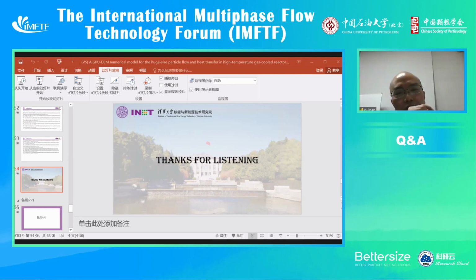Okay, if you use Voronoi cells to treat non-spherical particles, I think you can use a different number of faces to replace the non-spherical shape. And it is a simple geometrical problem to calculate the face-to-face view factors. When you sum up all the face-to-face view factors, you can get the overall view factor for this non-spherical particle to each surface of the Voronoi face. So I think it just needs some labor, but it's not a very difficult problem.